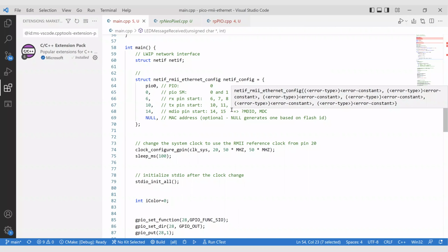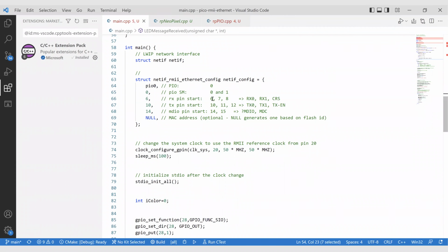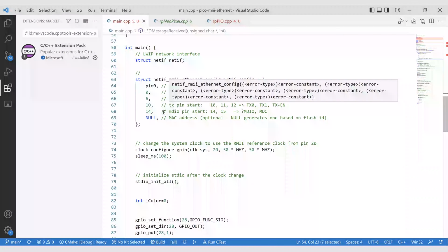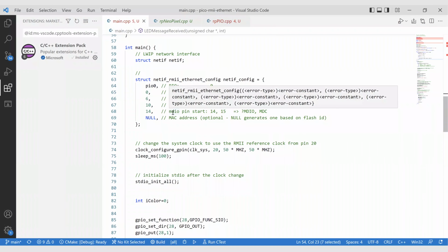Yeah. Oh my gosh. So anyway, moving along, there's a configuration structure for the Ethernet. Now, the Ethernet PHY, there's a standard interface to Ethernet PHYs. The original one is called MII, Media Independent Interface. And the idea is that the PHY is really the media, and it's dependent on the technology, where MII is independent. It's just a digital interface to the PHY. So that's the original concept.